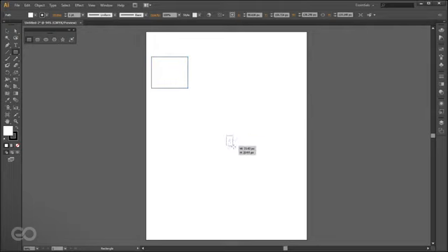I'll go ahead and click and drag. By default, it creates one corner point in that particular center, but instead holding Alt puts that as the center of my object itself. Now using multiple shortcuts like Shift at the same time, you can see that I can create a complete square starting from that center. So these are the two shortcuts which are quite useful while creating this.